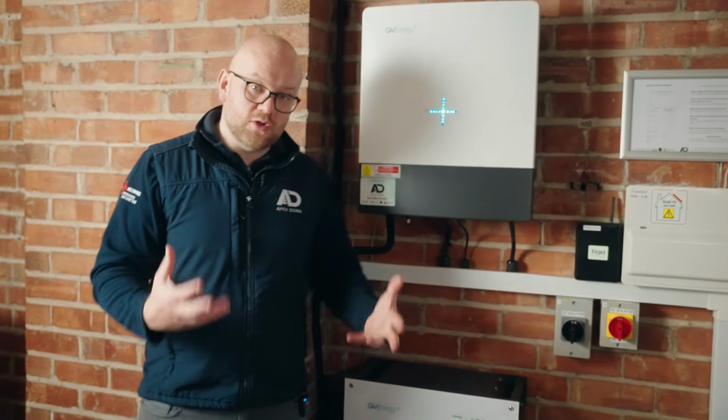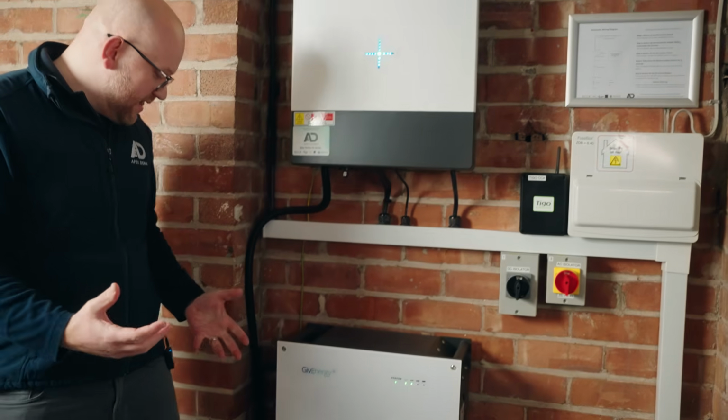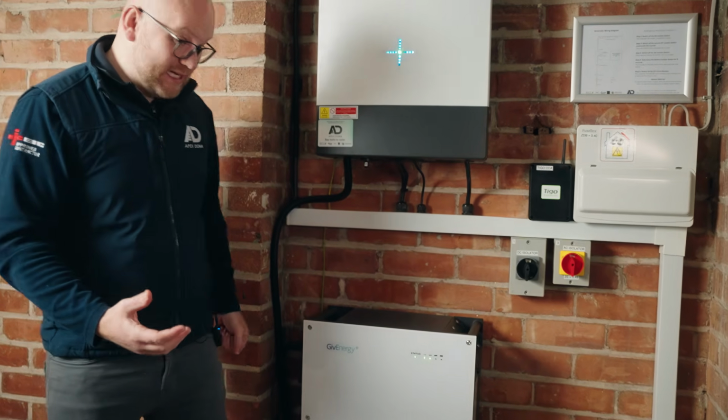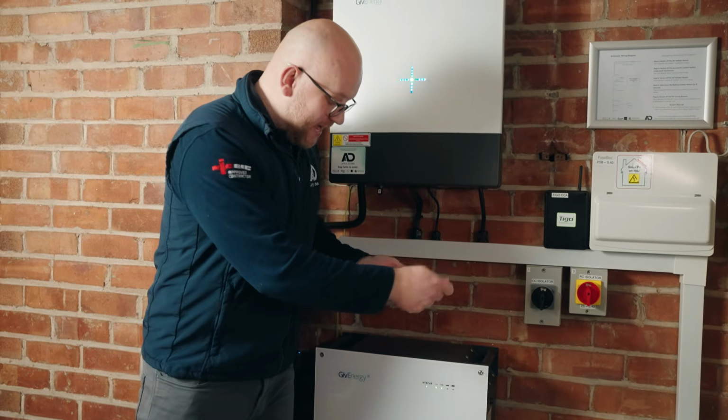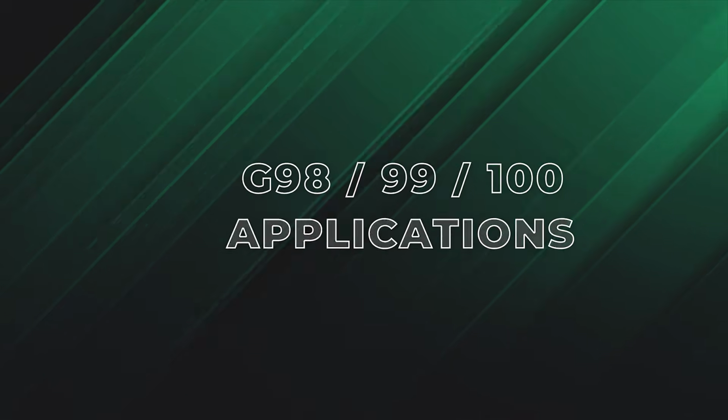Why? So if you look at this battery here, in order to be able to install an extra battery on this system, effectively all I've got to do is plug a lead in, mount the extra battery there, you plug the extra battery next to it, and you've doubled your capacity of the battery. It involves a couple of hours recommissioning it, setting the software up and stuff, but actually it's very simple, very straightforward to expand battery storage at ground level, as long as you thought about it in advance, saving you on that initial capital investment, and just allowing you the opportunity to try this before going whole hog and buying the biggest battery that you can get hold of.